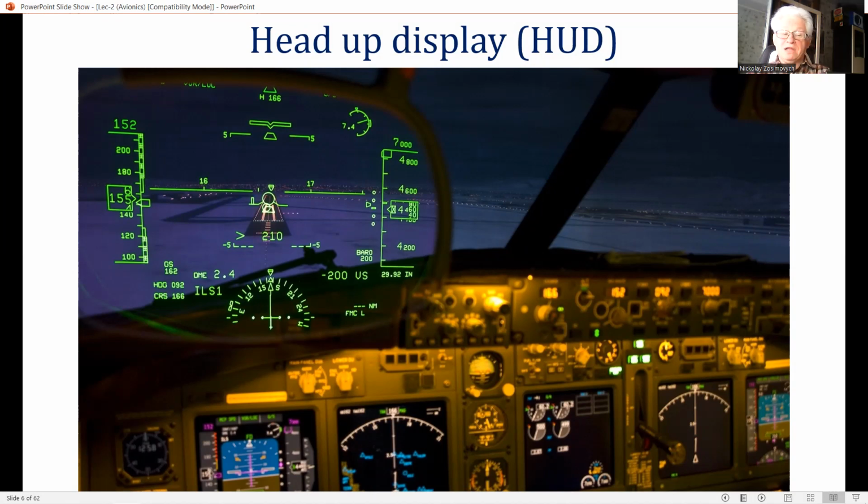There are no parallax errors, and aiming symbols for either a flight path direction or for weapon aiming in the case of a combat aircraft remain overlaid on a distant target, irrespective of the pilot's head movement. Right, consider sighting on a landmark using a mark on a window. The aiming mark moves off the target if the head is moved sideways. This effect is called parallax.